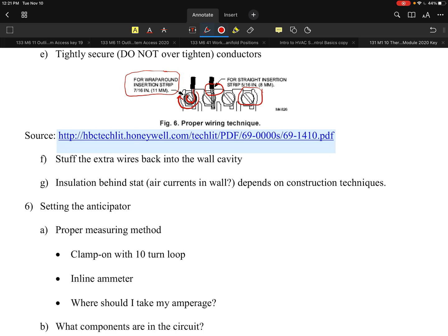I hate it when guys will do this: you've got extra conductors that you're not using, and you guys snip them off and cut them back. I'm talking way back. So those extra conductors are completely not usable anymore. So it's just something to be aware of, that can be a little bit of an issue.